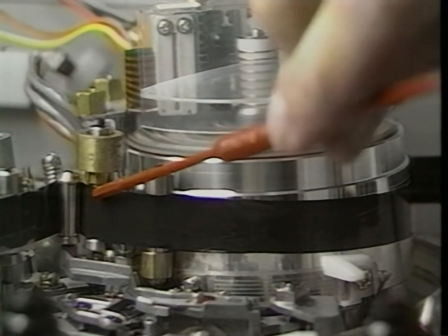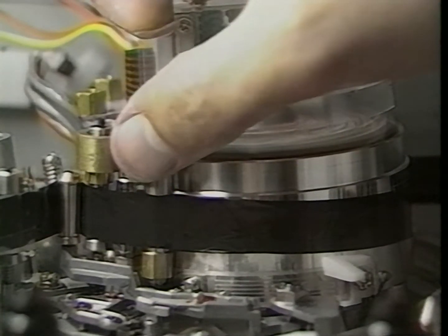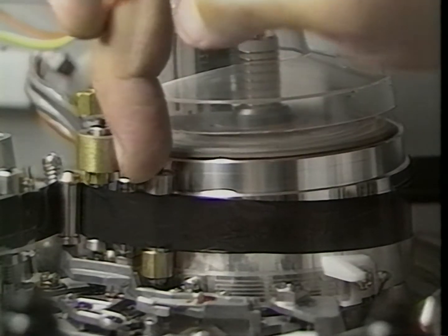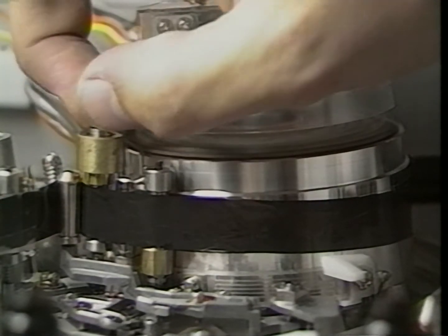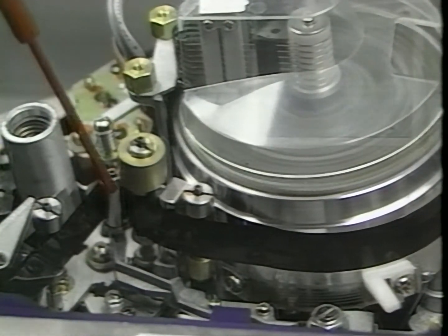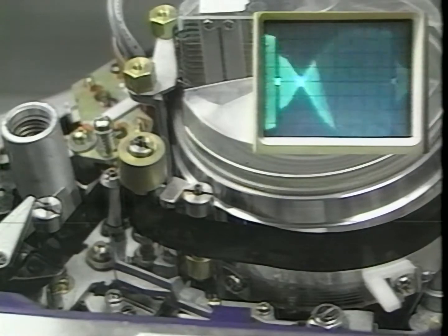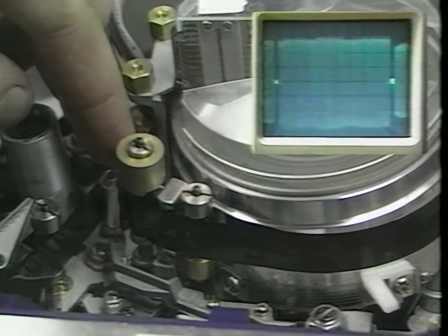Since the tension regulator is to be adjusted first, it is important that tape guide 1 and tape guide 2 do not influence the tape path. Clearances are made where the flanges of tape guide 1 and tape guide 2 contact the tape's edges by turning the adjusting nut at the top of the guide. The tension regulator's height now determines the entrance waveform. It should be adjusted so the waveform is flat at the entrance side.